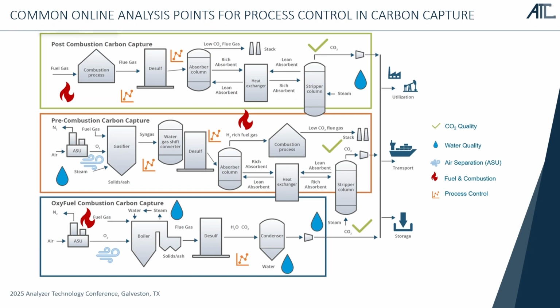And of course, it's a quality measurement. The pipeline cares about what's coming in, right? And if the CO2 that's coming in is off spec, it's going to be dangerous to the equipment of the pipeline, they want to be able to shut that plant in. So these measurements are occurring certainly before the CO2 goes into the pipeline, but then, periodically downstream of that as well. Lastly, we know in this case, there's measurements of the final quality before it goes underground.